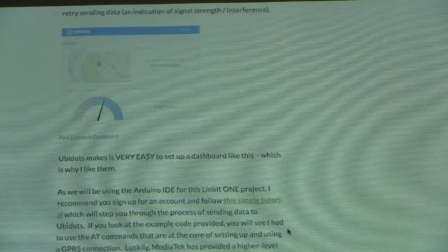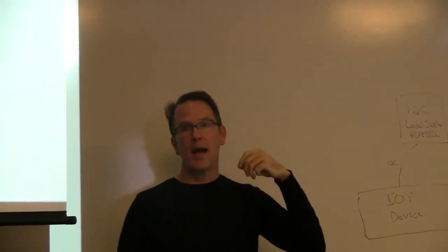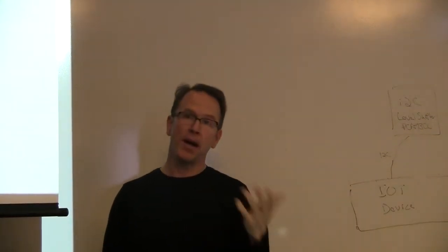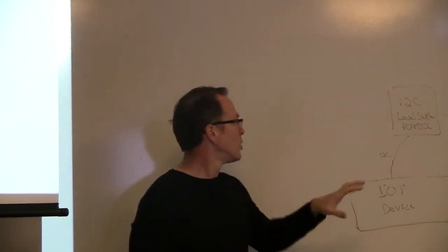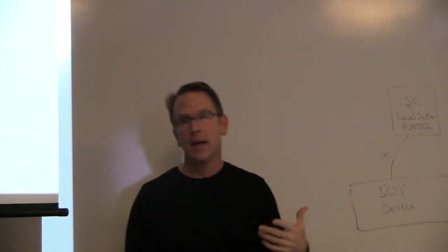Okay, where did you use the level shifter? Yeah, so I put a level shifter here because who knows, right? I thought, well, hey, if I'm building this thing and putting it up as open source and letting people take the board designs and even publishing the OSH Park, sharing the OSH Park thing, they might have a 5-volt device or they might have a 3.3 volt device. So the idea was to put this between the device and the sensors so it doesn't matter.